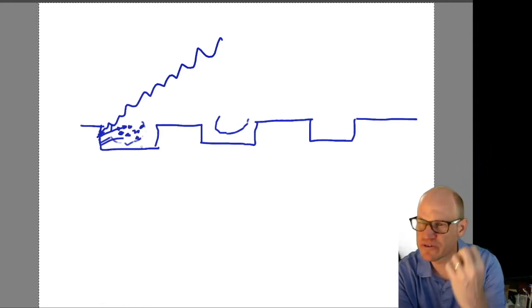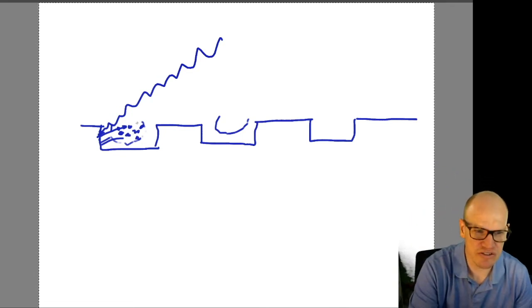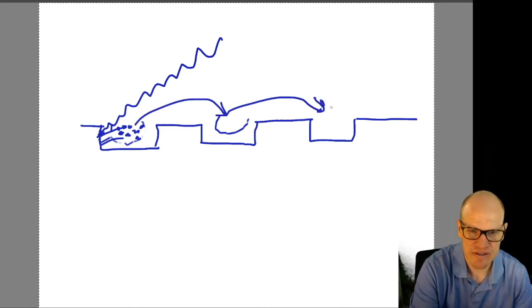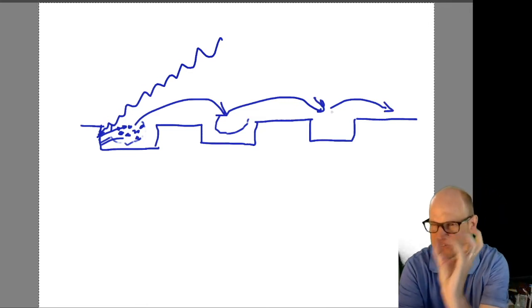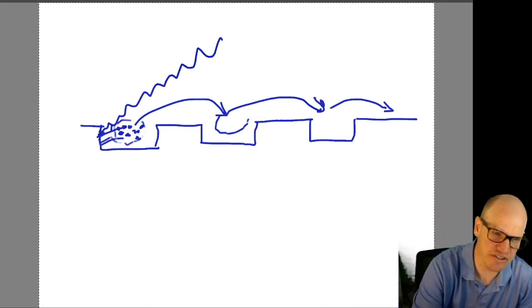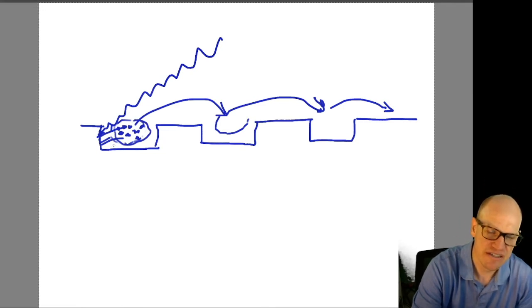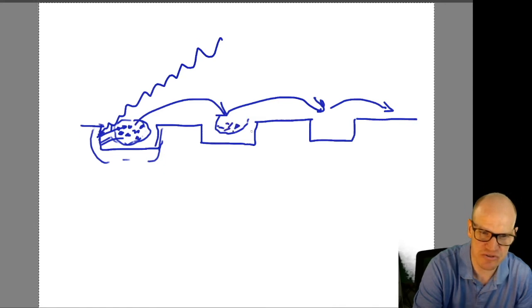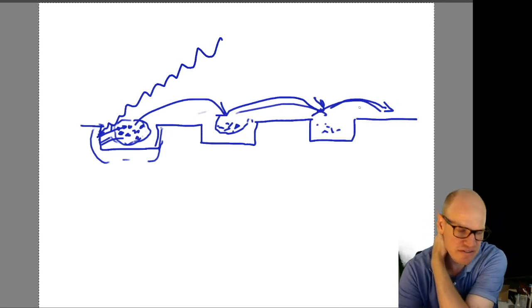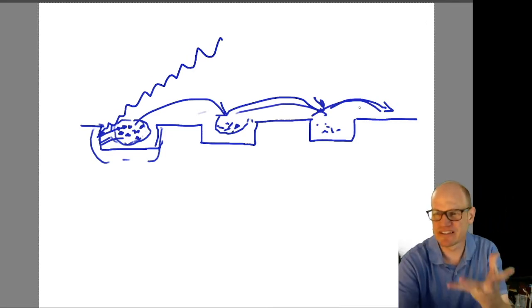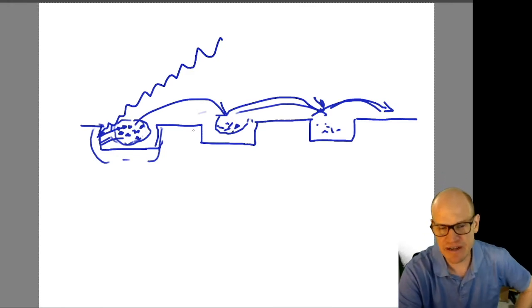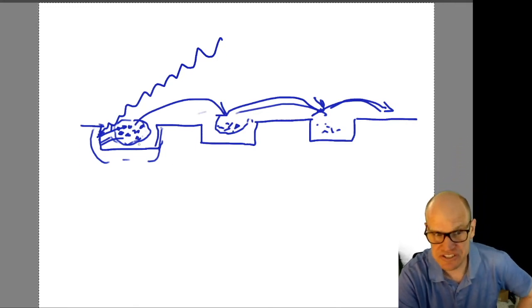And then when you render the image, these electrons are shifted one at a time over to the edge, and then shifted down to a device that counts the number of electrons. So you count the number of electrons that have been dislodged, and that tells you how bright the light was in this particular pixel. Each of these pixels is going to get its own collection of electrons. Those electrons are going to be shifted down to the device, I don't remember what it's called, the drain or something like that of the CCD chip, and counted up to tell you the number of photons that landed. So that's how a CCD camera works.